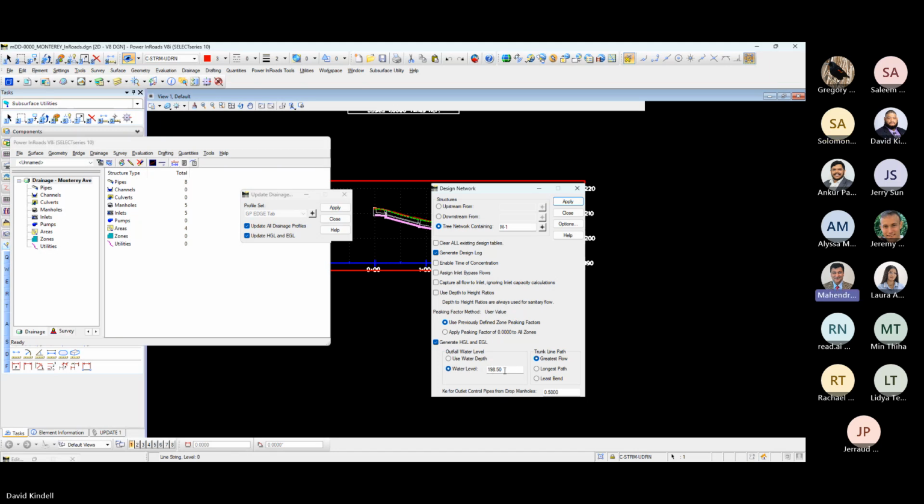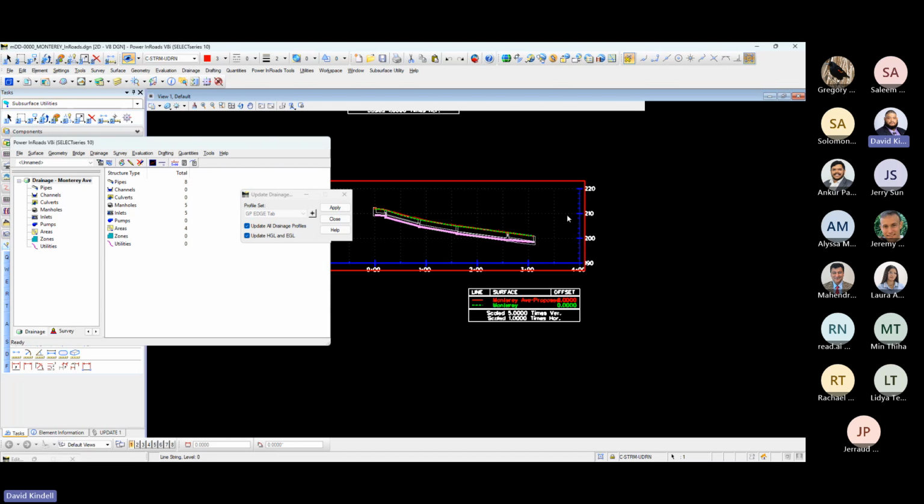And hold on, is there an option to put a rating curve? I'm not sure about that. Because we designed the storm drain for 10 year and the SGL is for 25 year. The 25-year water surface at the tailwater may be way higher than 10 years. So it is always better to seek options for the rating curve if there is an option. But if you want to do it for 25 years, that's fine.